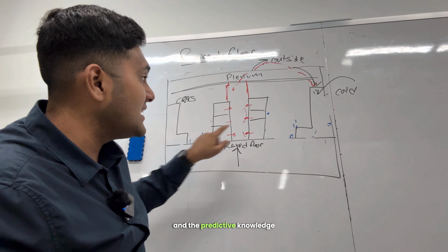So these CRAC units, or computer room air conditioning units, usually have 3 different types of ways they control their cooling. They can do it off of sensors, they can do it off of schedules, or they can do it off of manual configurations. The cooling system usually has a hot air return sensor above here. This is your return sensor.